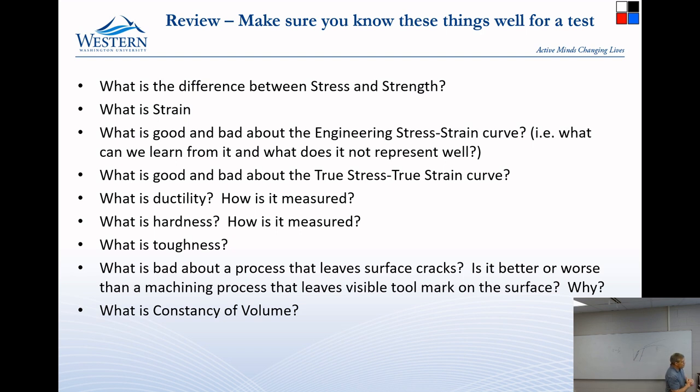People in the aviation industry were super excited when electrodischarge machining came out because it does not matter how hard the material is. It machines exactly the same. The melting temperature of the material matters, but how hard the material is is completely irrelevant. So when this was a new process, they were trying to do a lot of machining of titanium to make light parts for big planes. And they were very excited about it.